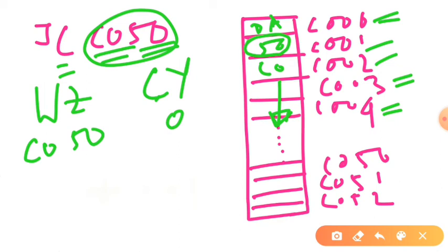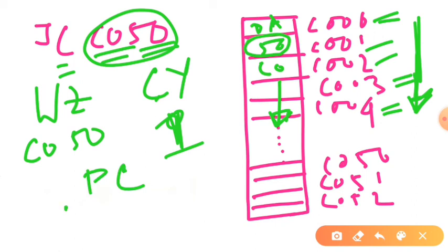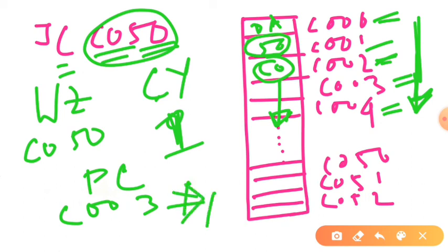So it was our default way of program execution, right? We follow that. After C002, then C003, then C004 in this way. But if we consider that the content of carry was previously 1, then what will happen? Then the program counter's content, which was C003 after reading the higher order byte of the target memory address from memory location C002, obviously that will not be placed to the address bus.